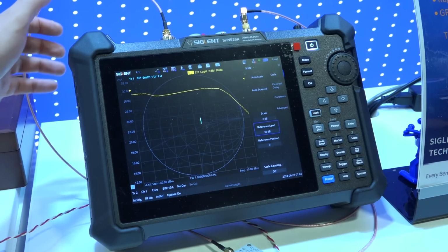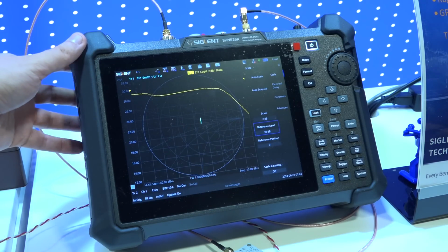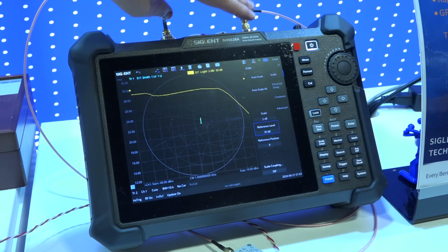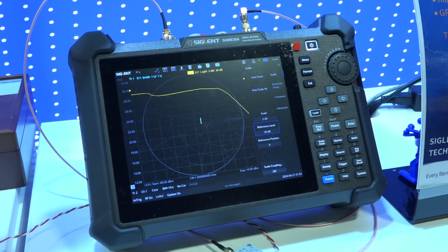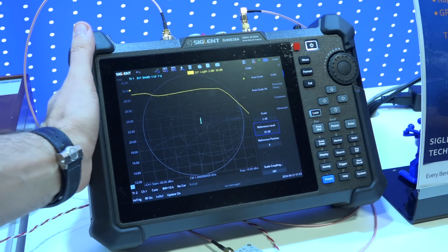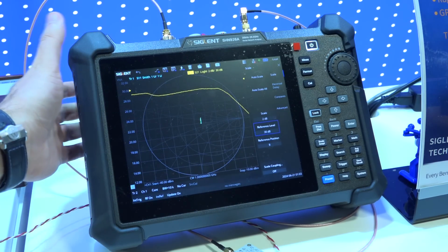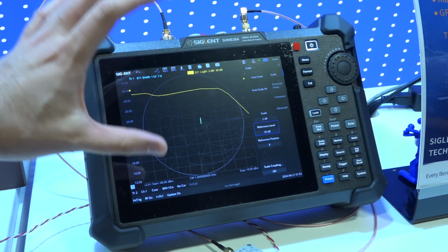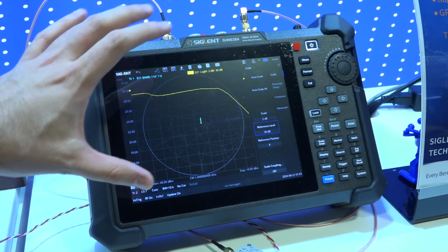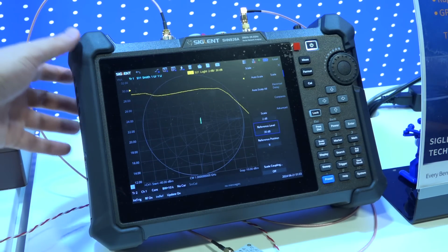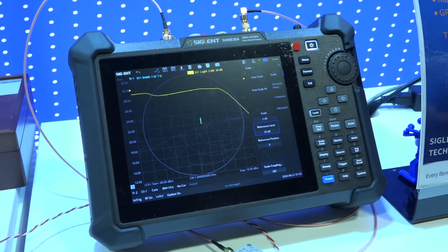And now we have the handheld spectrum analyzer, network analyzer combination as well, up to 26.5 gigahertz. This is actually a complete 2-port system, so you can do full 2-port network analysis directly on the module, with over 100 dB of dynamic range, and of course it's portable, handheld. How long does the battery on this last, typically? 4 hours of operation, up to 26.5 gigahertz. And if you notice, all the software across the entire product portfolio is the same. So that's got that consistency which all the vendors are looking for. It's nice to see here too.